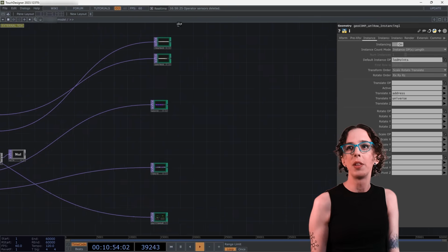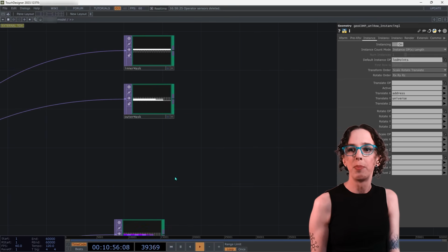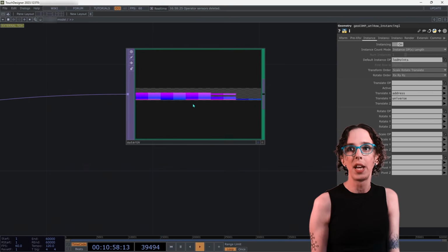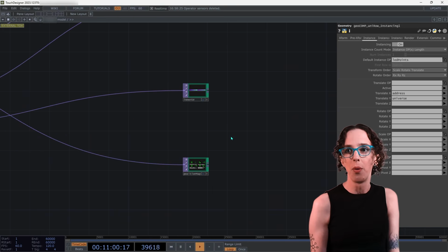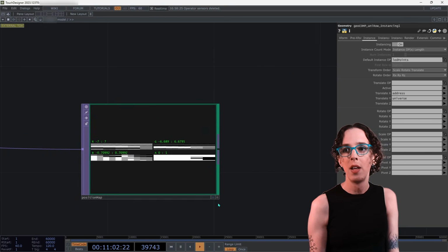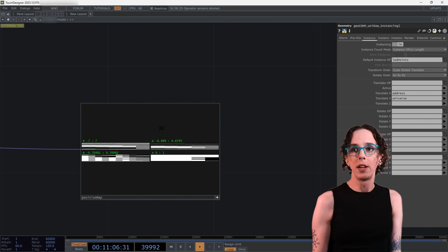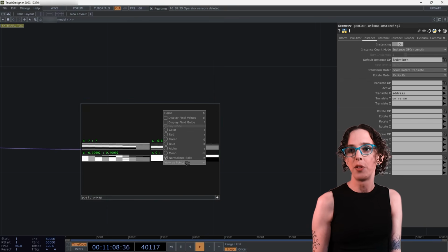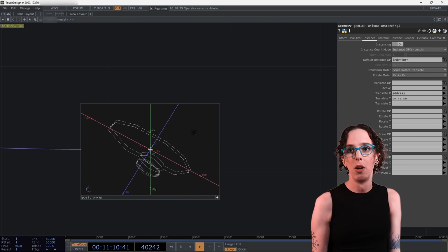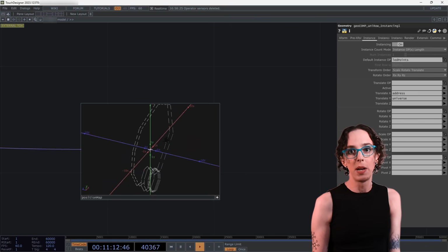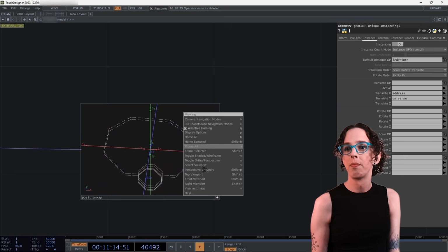There's a bunch of stuff in here, but the end result are these TOPs with per pixel data that indicates where everything is and so on. So for the position one, if you right click it and in the viewer do view as points, then it'll actually show those positions, basically as they are in the previs.